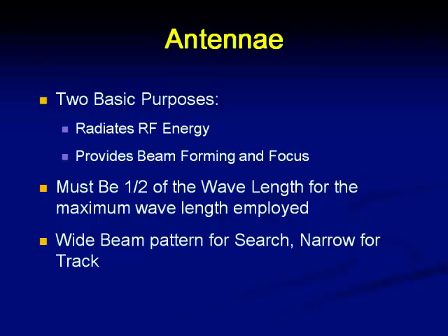Now let us concentrate on the antennas that will be used in the radars. What is the purpose? There are two basic purposes. One is it should radiate the RF energy, and we should also be able to send the energy in the desired directions and restrict that in undesired directions. That is what we call good beam forming and focusing.